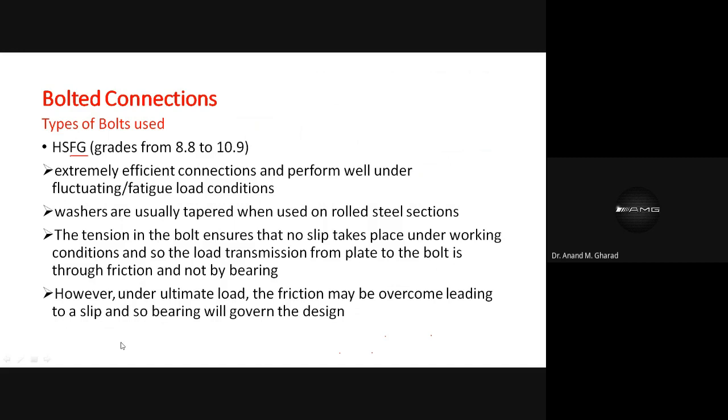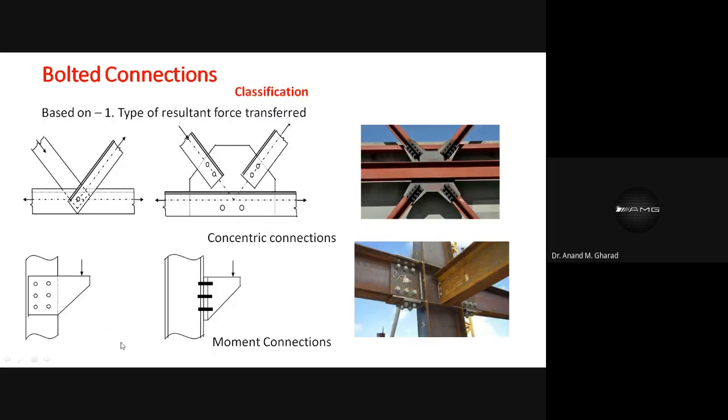We cannot deny that the load cannot go beyond a specific limit. It may cross that limit, and when it crosses the limit, that is when the complete frictional resistance is taken care of by that load, then it enters into the bearing action. Bearing action, as I have told you, is that the plate body and the body of the bolt, when they come in contact with each other, then the load will be transferred through the force which is exerted by these two different materials. Okay? So fine.